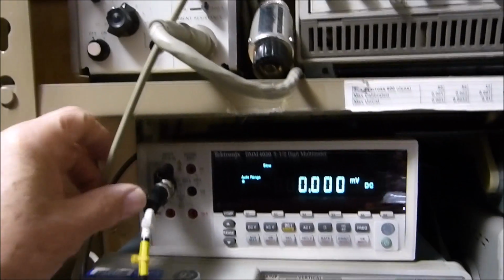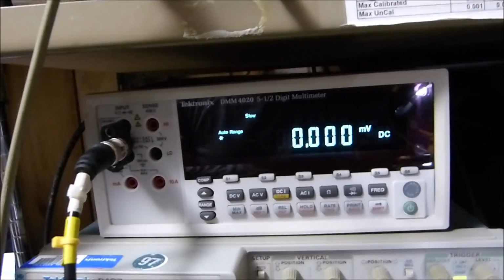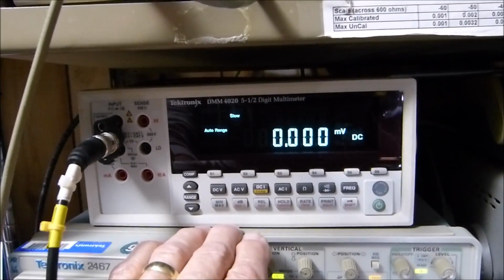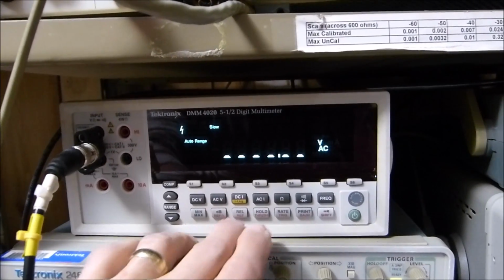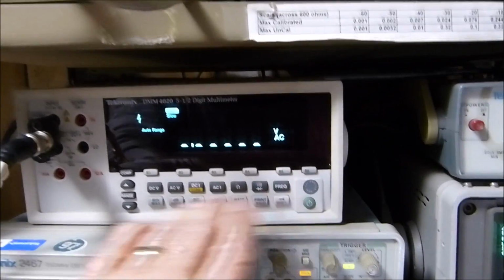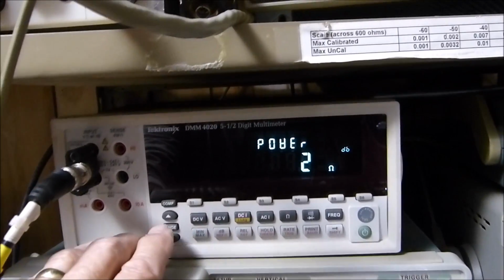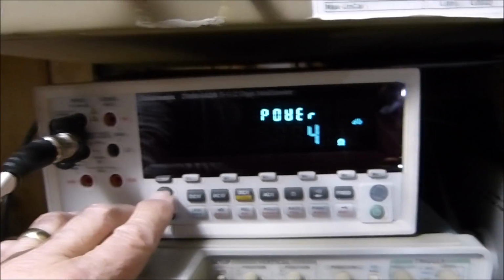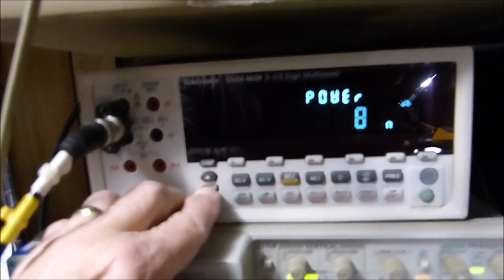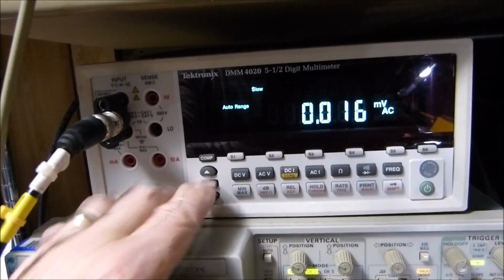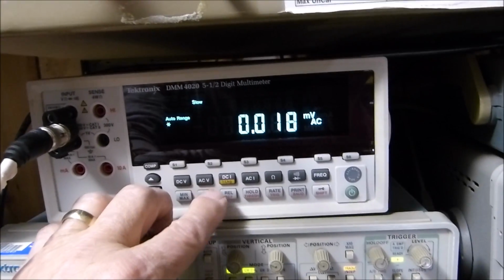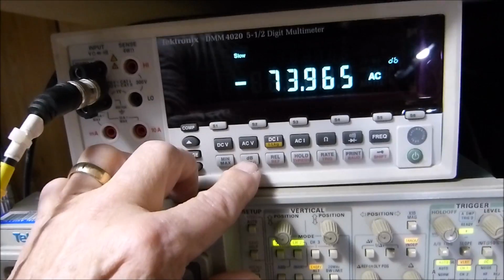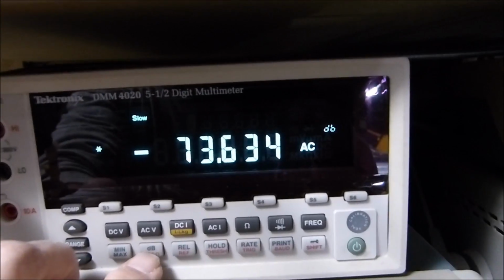Here is a really nice little Tektronix meter. It's called a DM4020. Let me show you what you can do with it. Besides measuring AC and DC and all that stuff, you go right here to this, and then you set the impedance range with this knob or button. Set it to 8, and then press and hold range till it clicks. Then you would actually go back to make sure it's on AC. It is, and then you start hitting this little knob right here, and see there you're measuring dB gain.